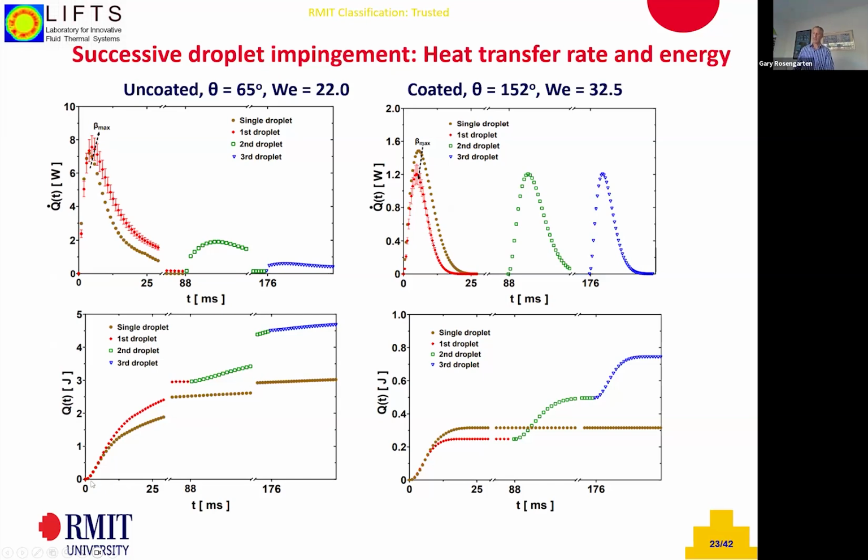So what this comes out as now, if you look at the integrated energy, how much energy is being taken out of the surface by integrating this as a function of time, then you see that every time that droplet hits, it's taking out less energy. So you come to a maximum as well, just hits this film, it stays on there, it's hydrophilic, and eventually it might drain. But you're always going to hit some kind of liquid film, so that it starts to increase much more slowly. On the other hand, each time the super hydrophobic surface is exposed, the droplet takes out less energy. You can see here 1.2 to 6 or so, but it continues on.